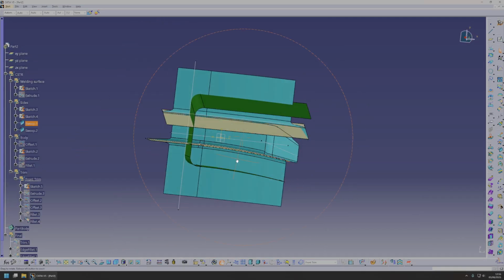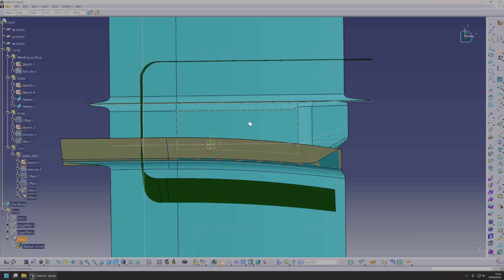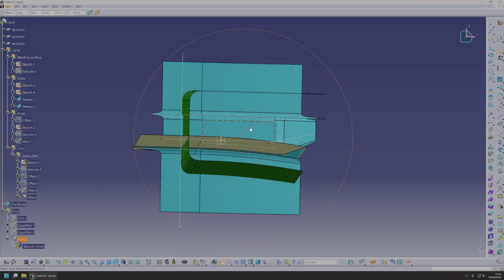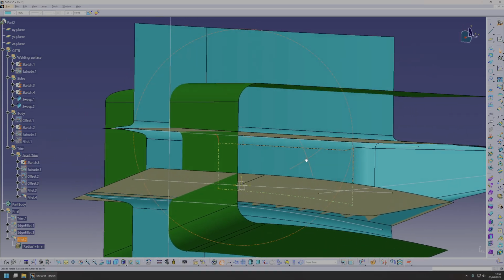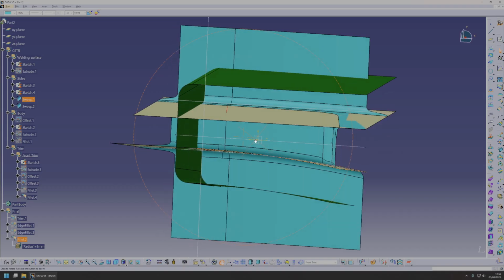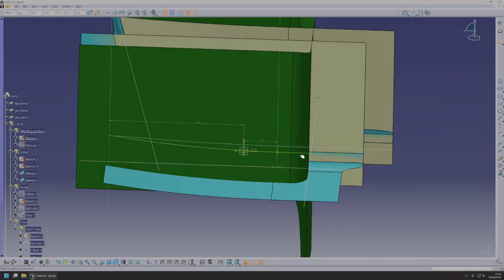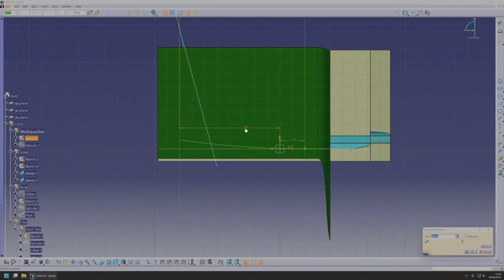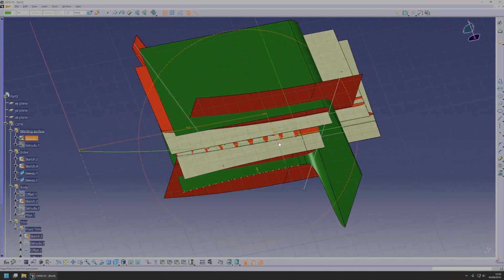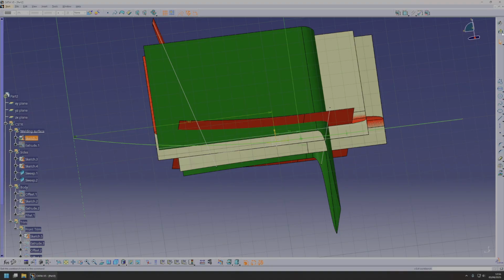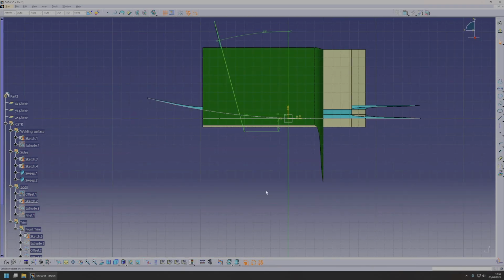Right, now looking at this part, we noticed one thing, and that is that it's pretty small. It's a pretty small part compared to what I had in mind. And this is a 5 millimeter radius, and it looks really big on the part because the part is very small. So we can go ahead and change that already. How do we do that? We go into the sketches that we first did, and we change this. This one is non-constraint. We go with it like that, and then we need to change this as well.